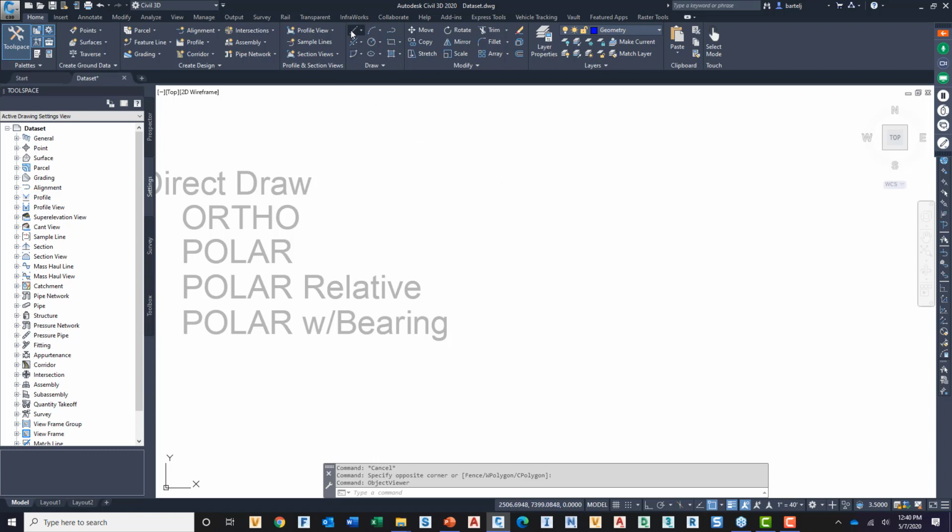I'll go ahead and create a line. We'll just pick a point in space here. We'll say I want to go from this direction. As we move the cursor or the crosshair away, I can give it a distance. I'd like to go 10. I'll hit enter. It goes 10 units, 10 feet or so, whatever it's set in the drawing. That direction, 20 in this direction. Okay, that's great, but they're kind of random numbers.